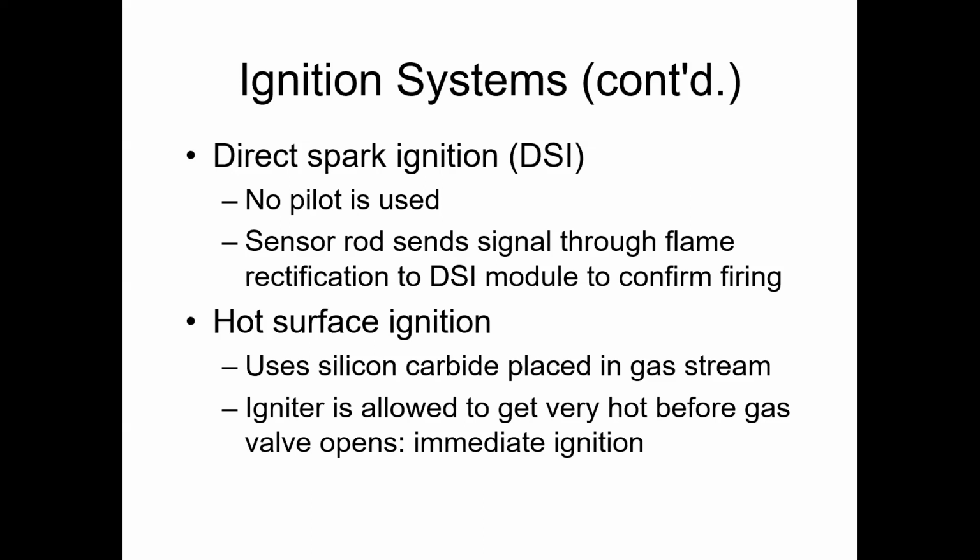This igniter is going to be tested one way, and I'm going to explain that to you in a second, because question number 6 for tonight for your attendance: how do you test a hot surface igniter? You are going to test it with resistance. You're going to check for resistance on a hot surface igniter. It's got 2 wires feeding into it, so you check from one to the other. Usually it comes in a plug, and you can just undo the plug, and then check those 2 leads on the other side of it. You'll check with ohms or resistance on your meter.